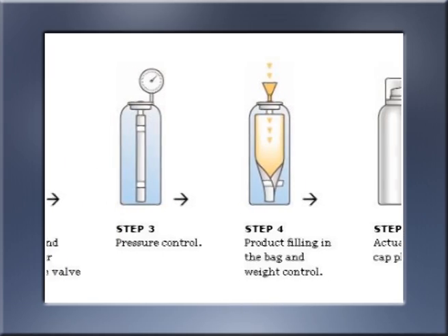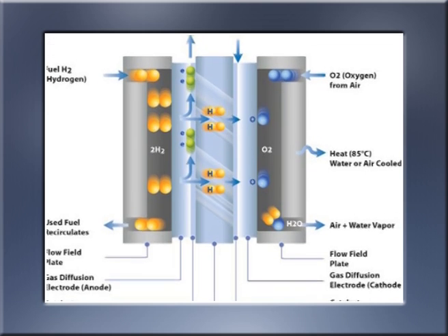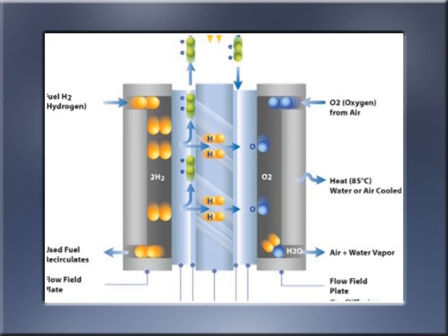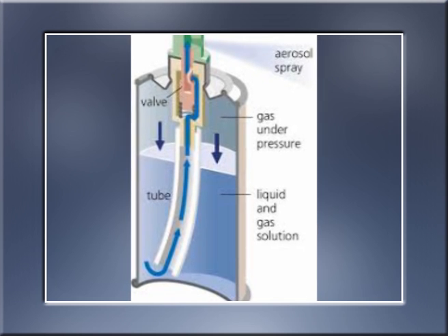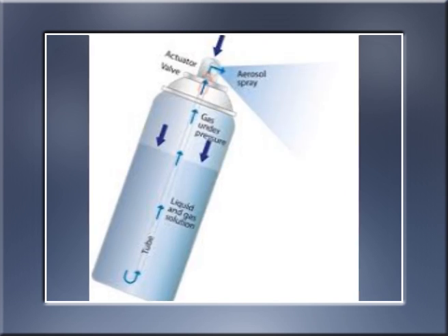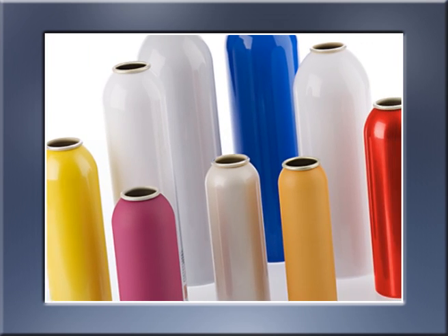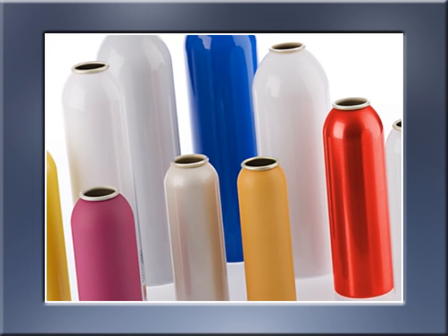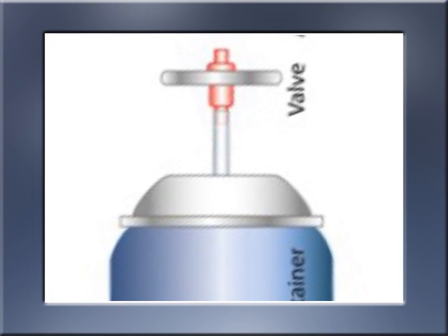Tin plated steel containers are lightweight and relatively inexpensive. For some products, the tin provides all the necessary protection. However, when required, special protective coatings are applied to the tin sheets prior to fabrication so that the inside of the container will be protected from corrosion and interaction between the tin and the formulation. The coating usually is an oleoresin, phenolic, vinyl or epoxy coating. The tin-plated steel containers are used in topical aerosols.